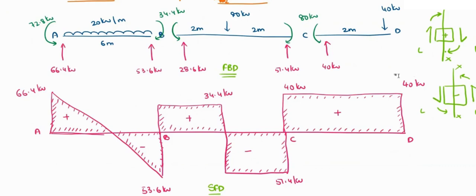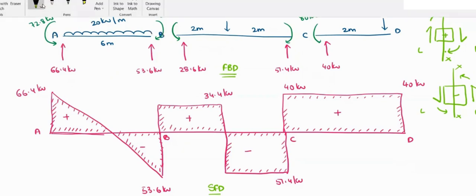Okay, then after drawing your shear force diagram, we are going to make a bending moment diagram. To draw the bending moment diagram, we'll just see. Due to the external load acting, the bending moment diagram acts like a simply supported one. For these reactions, you're going to have the bending moment diagram to be a parabola. Then afterwards, the intersection portion will be your final end moments. So we'll see that.